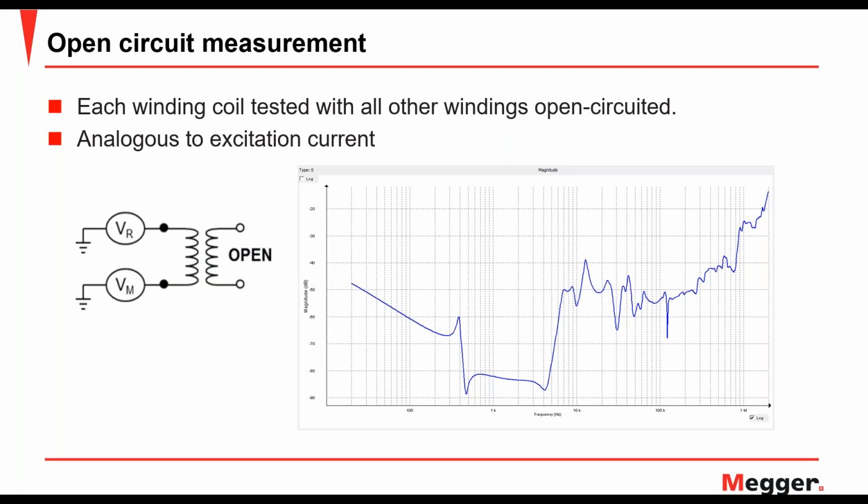The excitation current that the transformer winding draws depends on the condition of the core and the winding, because the current essentially depends on the reluctance that the flux sees when it flows in the core. So if the core is corroded, if there are any defects in the core, then it will see a higher amount of reluctance. It'll draw more current. So things of that sort are related to excitation current. Any problems with the core, or if the winding has short-circuited turns, that will cause a problem as well. So any problems with the core or the winding could be detected using an excitation current test.